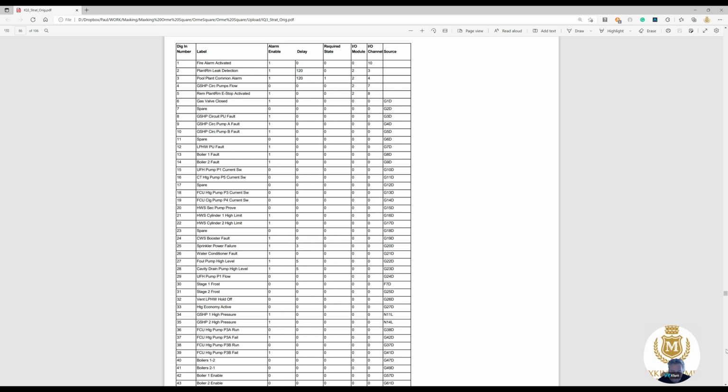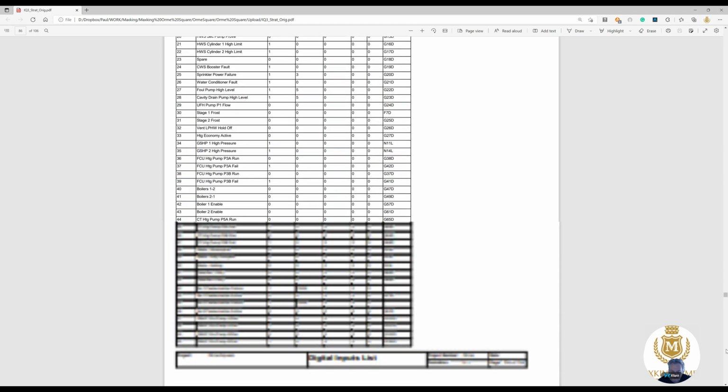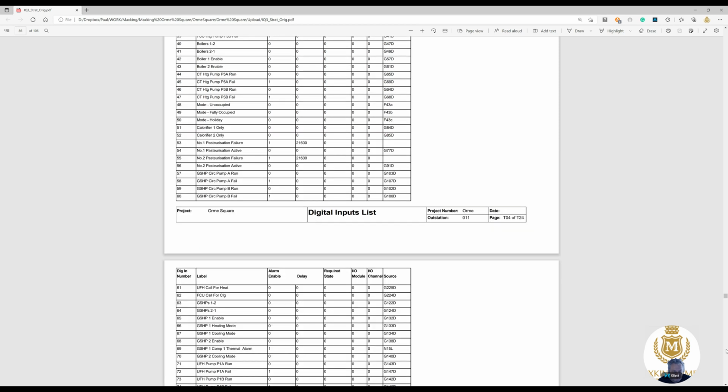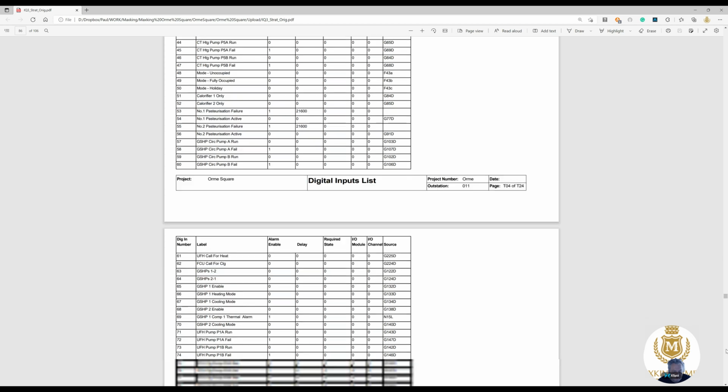They're using a Modbus to Trend Synapse device, but I don't need that. I can talk Modbus IP direct to the heat pumps. Don't need any of that.